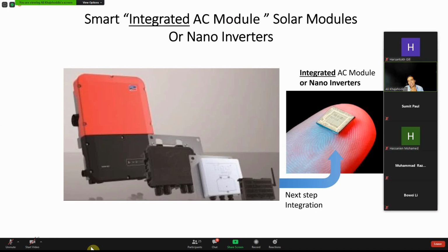Just imagine, in that size chip, even if you dissipate a tiny amount of power, like, let's say 0.4 watt, 0.2 watts, it's going to increase the temperature of that piece by maybe 100 degrees. So it's going to melt it because it's too small and it cannot dissipate the heat easily.